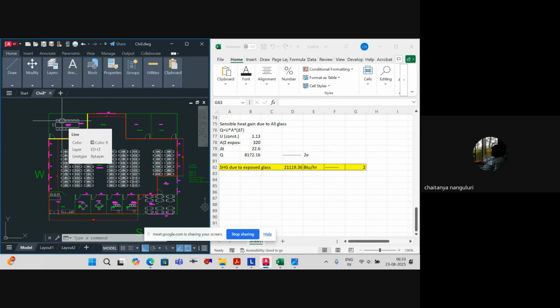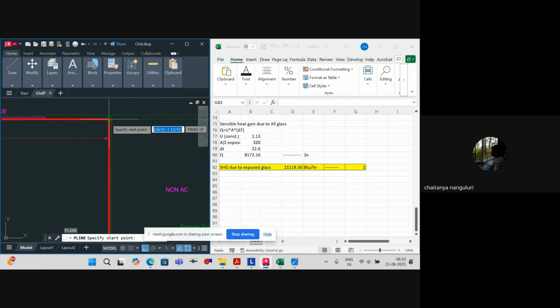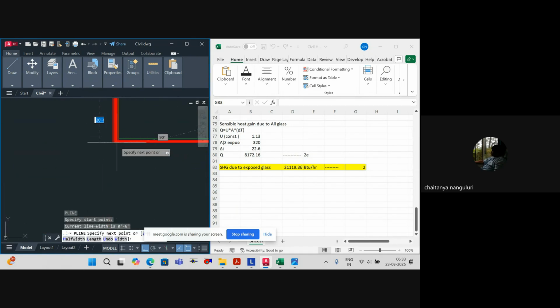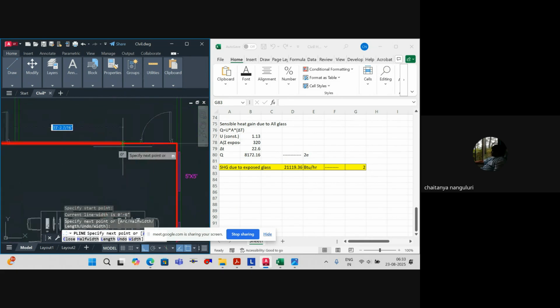You agree? Yes. But let's say, can you give a guarantee that when the client is using workspaces, the conference room AC will always be on? Whenever the meeting is scheduled, only then is that AC on. So worst case scenario, it could be off as well. You agree? So we have to consider it as a partition wall. Though it's an air conditioned space, you have to understand whether during normal conditions it will be on or not.